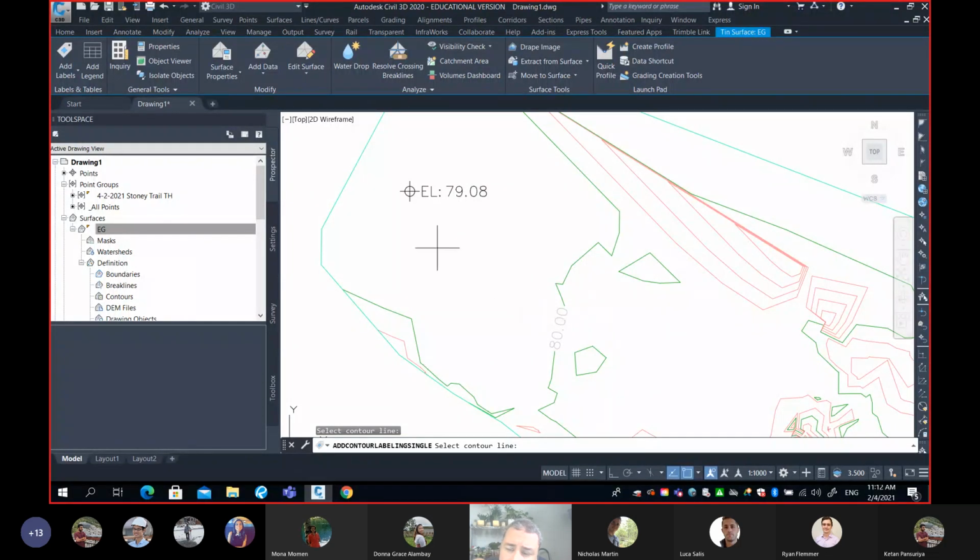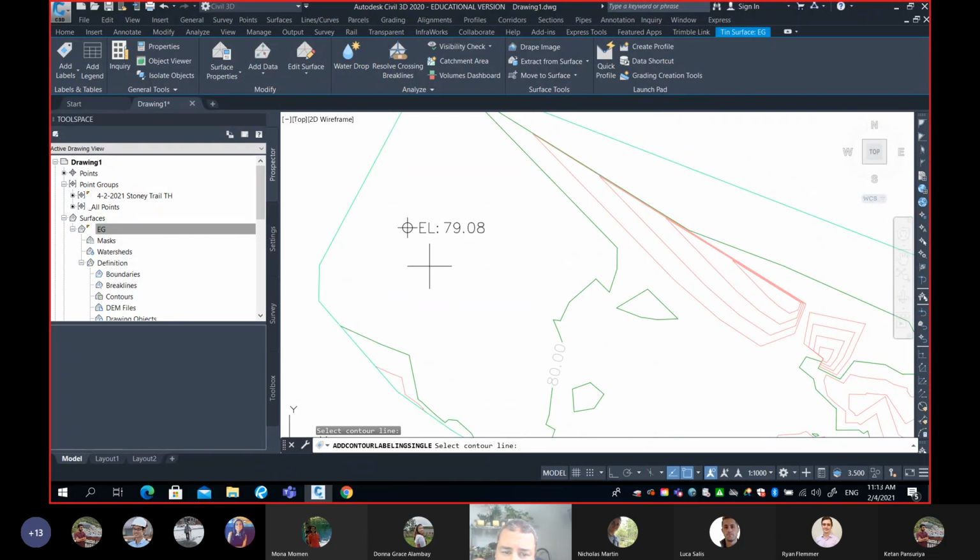is keeping down. So bottom line is, when I ask you, please add for me spot elevation wherever required, don't just go ahead and throw for me any points. Following, you have to add spot elevation wherever you see a closed contour line, and also on the border. Bottom line is, wherever you have a confusion and the contour line doesn't give you a full picture of what's happening, then add spot elevation to clear the confusion. Is that clear? Yes.